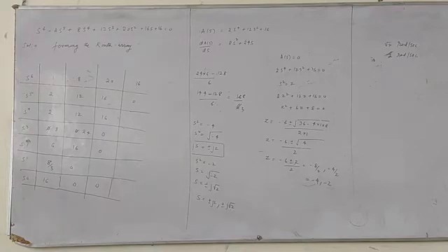There we had written something earlier about a stable system: since there is no sign change in the first column, the entire will carry no roots. Just cancel it. We have just written that we have confirmed that there are no roots on the right half of S. A stable system will not come. Just cancel it. But this is a clear-cut confirmation that there will be no roots in the right half of the S plane. That doesn't indicate that the system is stable.